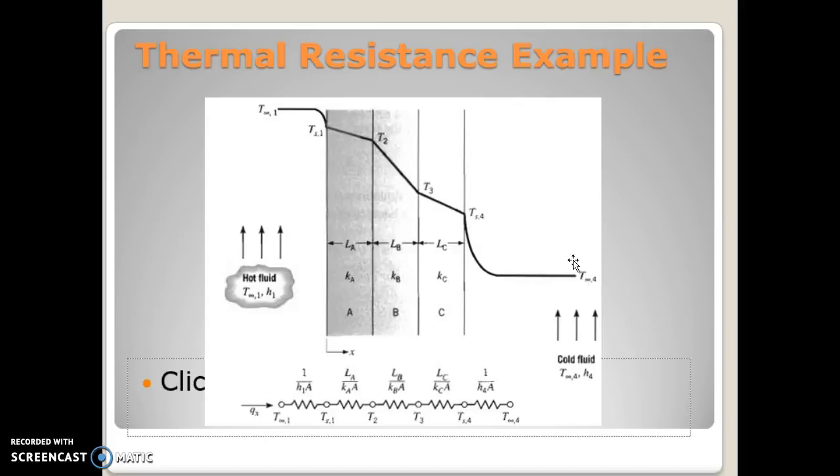So you have the lowest temperature here and you have the highest temperature here, and as there is convective heat transfer between air and the solid wall here, while there is conduction through the walls, but the conductivities are different, so the temperature drop slopes may be different. And this is again the convective heat transfer resistance on the inner surface, or that offered by the air layer on the inner surface.